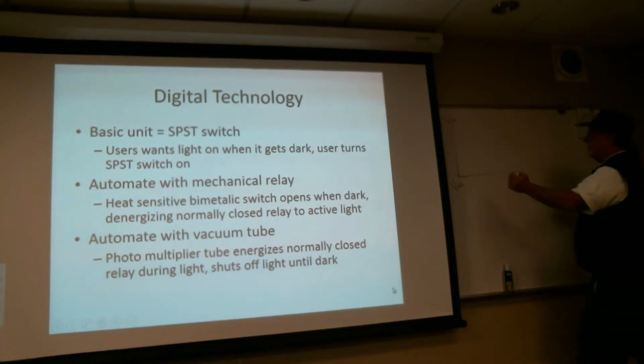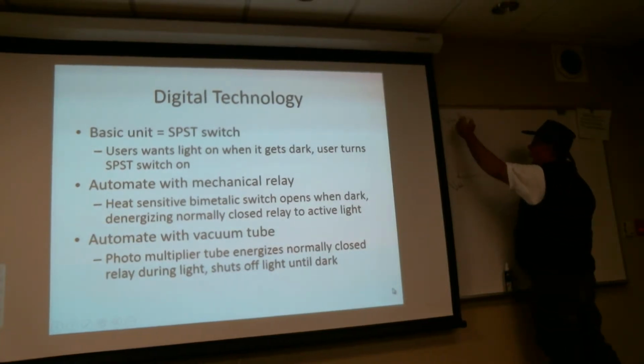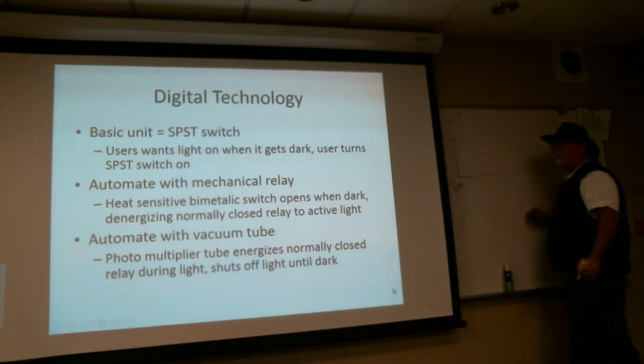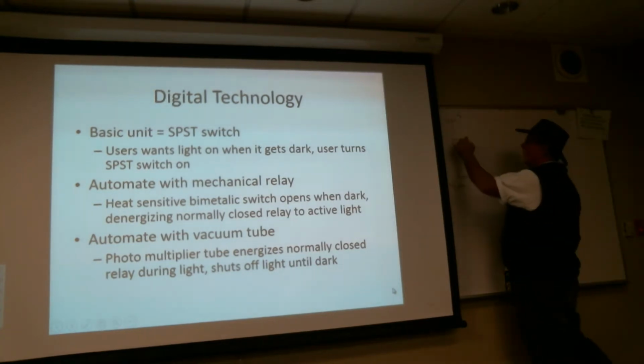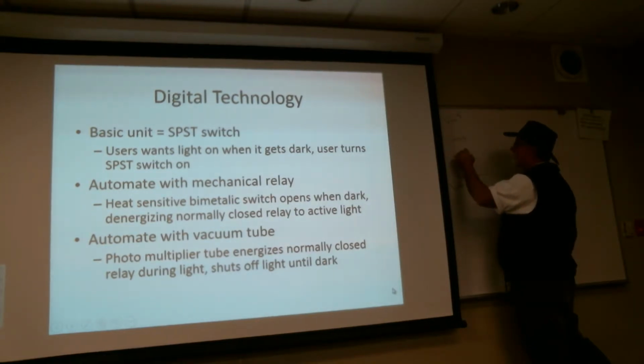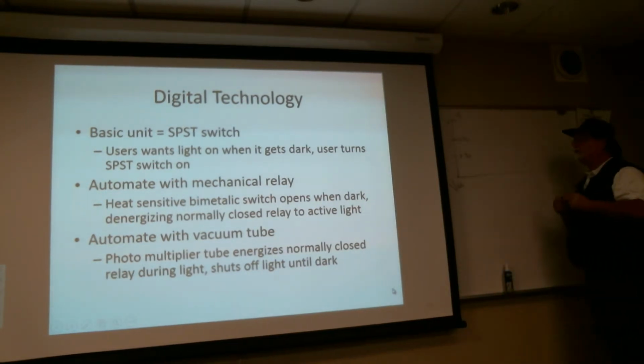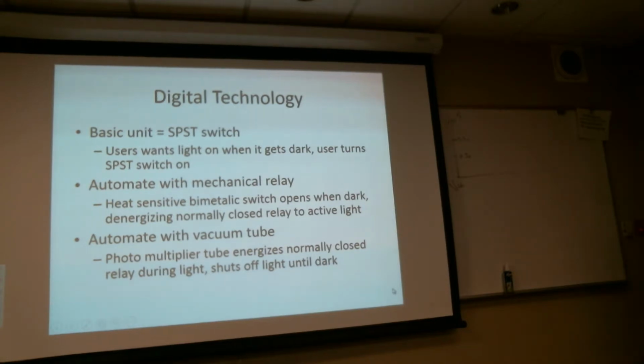So we'll pick a value. Let's say in this case it's 5 volts. What we're going to do is pick a couple of threshold values, and those would be put out in the spec sheet for whatever the integrated circuit is. And we're going to say this value, oh, I don't know, let's pick one, 3.3 volts, and here we'll say, maybe this is, let's call it 3 volts, right here. So those two values are going to be my threshold voltage, right?